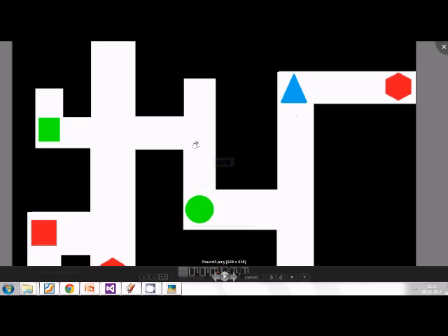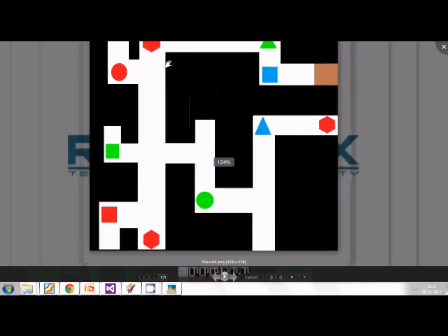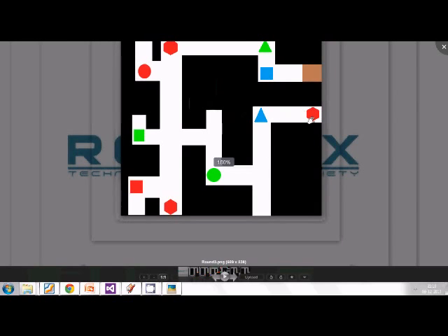That means in my original map processing, I assumed I would approach from this side, but instead I'm approaching from this side. So I'll just do a U-turn. You can make a separate case in your code. I'll just do a U-turn and then follow the path as I would have otherwise. So here U-turns will also become important, particularly when you're visiting these red hexagons, especially ones at dead ends. So you'll also have to understand how and when you need to use U-turns.